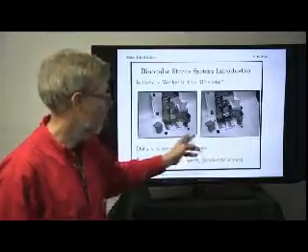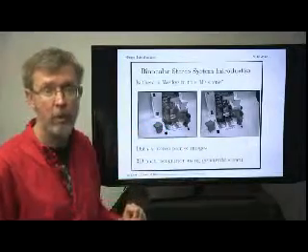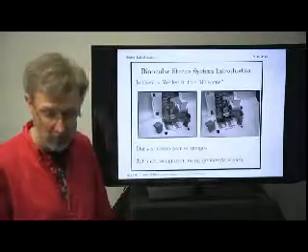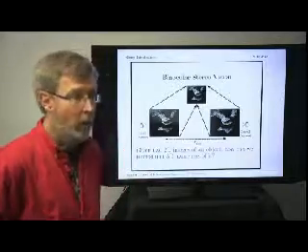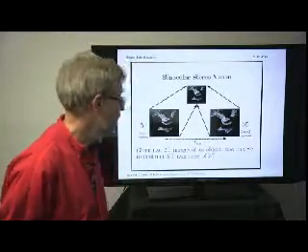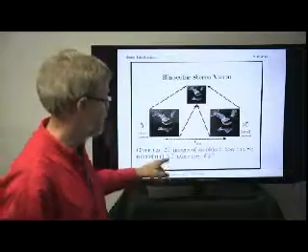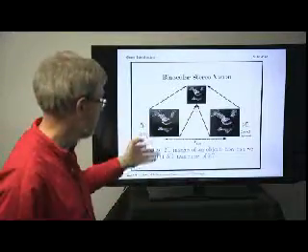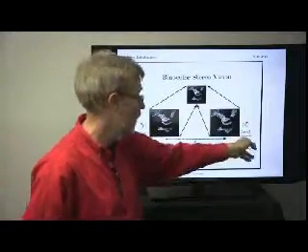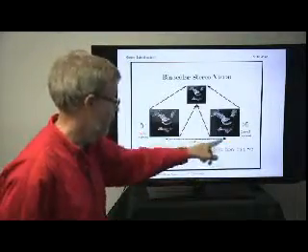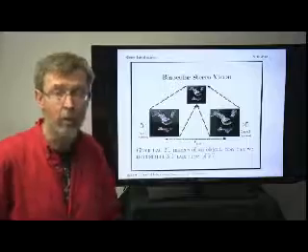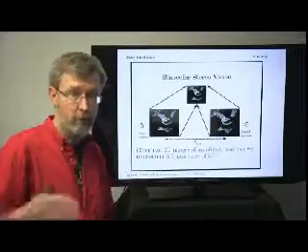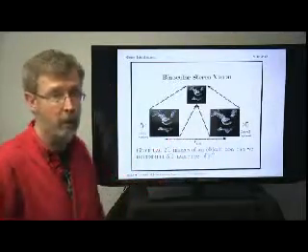One of the things you might also want to do is, if you can do cross-eyed stereo or wall-eyed stereo, you can look at this pair of images and actually see the three-dimensional scene if you want. The core of binocular stereo is really to take the pair of images and somehow combine them to produce some sort of three-dimensional description of the scene. We typically have a left video camera and a right video camera, and they've got to be separated by some kind of distance, a so-called baseline. And once you've got that, you can triangulate out from the right camera and the left camera to figure out the three-dimensional position.